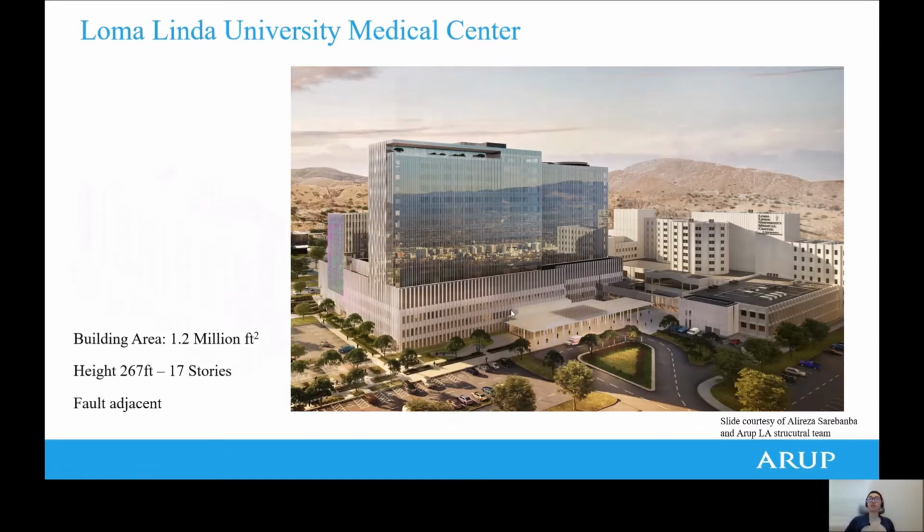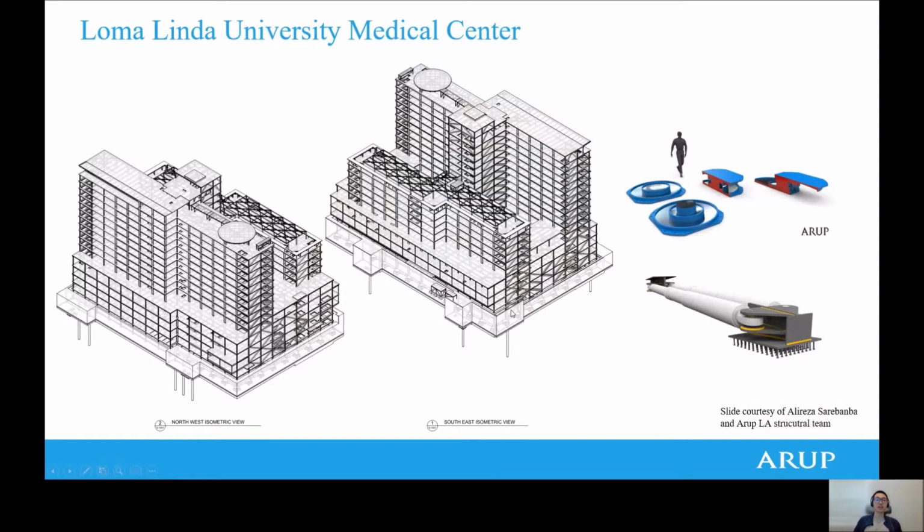As you can see on the left, the superstructure system is buckling-restrained braced frame and moment frame for the two lateral directions, respectively. In order to achieve the desired performance under extreme seismic conditions, a seismic isolation system is used, which consists of triple friction pendulum isolators and viscous fluid dampers to control the horizontal displacement, as shown on the right.